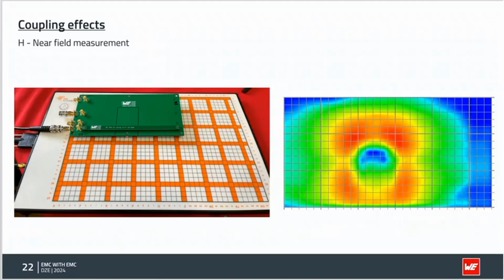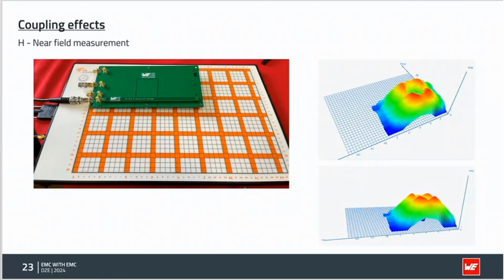But what do you see now? Well, you see something really nice when you change to the 3D view. You see we have no field in this area. Also nothing in that one. What happened? Well, here we have the transmission line directly over our ground plane, so the generated magnetic fields can cancel each other out, and they will, but only if we let them.